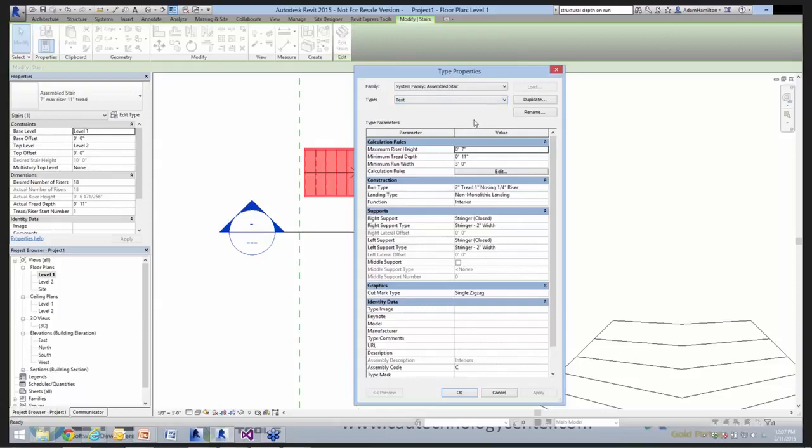Okay. Now, with each stair type, we've seen people create stairs and start to manipulate them, because you can stretch them and make treads bigger, smaller, or things like that inside the project after it's drawn. But the default calculations here are just defaults. They're a good start point. Now, just a little tip and trick: 9 times out of 10, a stair is never going to stay at 3 feet. So usually with anything, I change this to 4 feet, change it to 5 feet. It just helps me each and every time, so I don't have to modify it so many times.